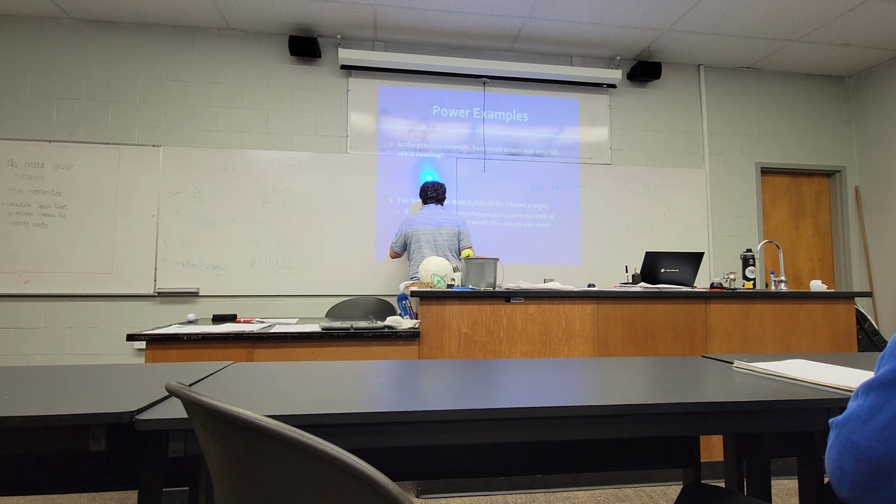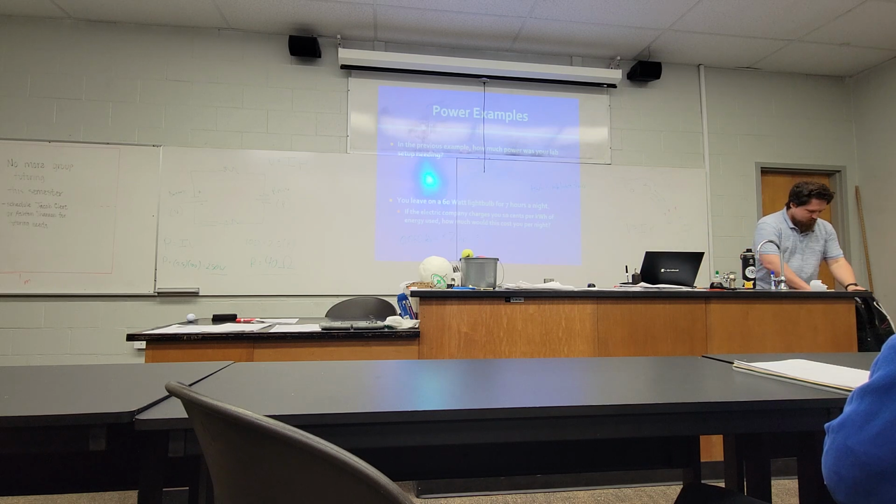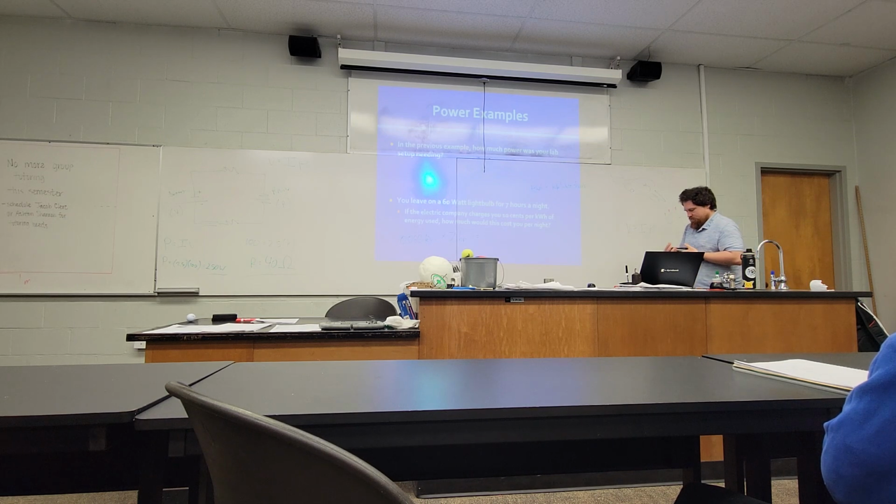we're going to take its wattage, convert it from 60 watts to 0.06 kilowatts. We multiply that, and I'll write in the units. So this is the bulb, this is its wattage in kilowatts. We're going to multiply that by 7 hours, and that will tell us the energy that the bulb uses in units of kilowatt hours, which is the unit that U.S. electric companies use to bill you for. 0.06 times 7.